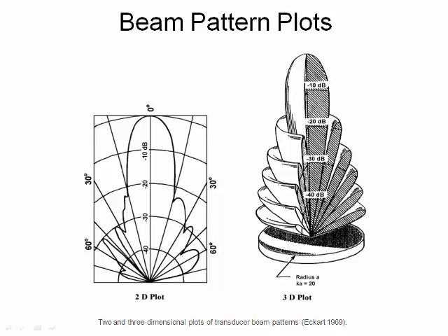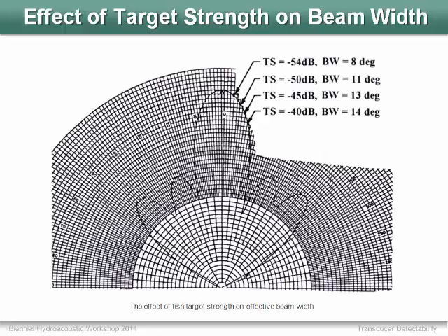for a given threshold. Say you're set up to detect a minus 56 dB echo as your smallest threshold. Really, that beam width is just breaking 0 degrees as you move above that 56 dB target, and then as you get out to 6 dB down to your minus 50 dB fish, then your beam width would be that nominal beam width, and then as you get into larger fish, and this next slide shows that a little bit.